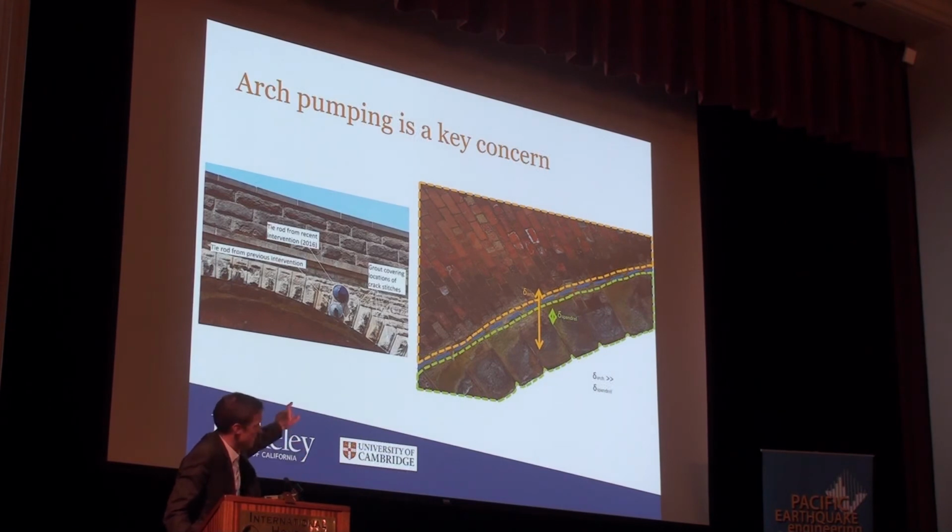So they've currently stitched all the external stones back into the main part of the bridge. They've stitched those together and grouted them in. But it's well known that that doesn't last very long because of the stiffness, the differential stiffness problem you have. So they know it's going to start pumping again, and that's one of the things we want to measure.